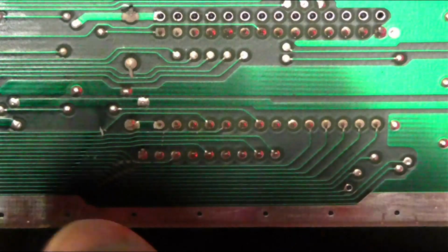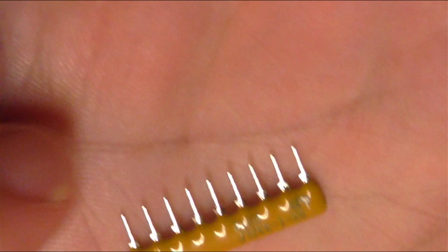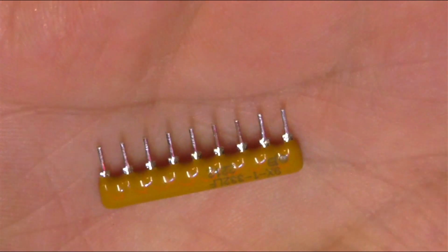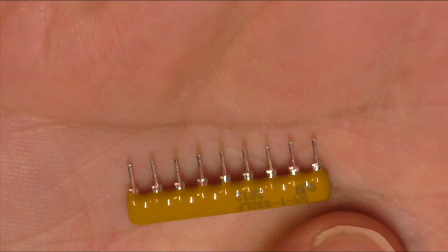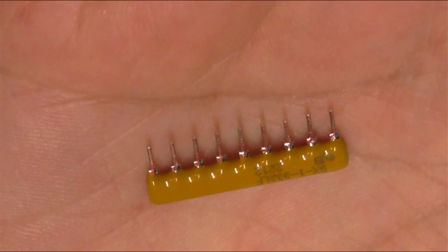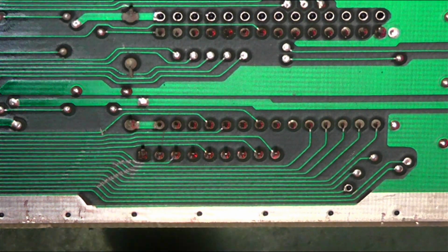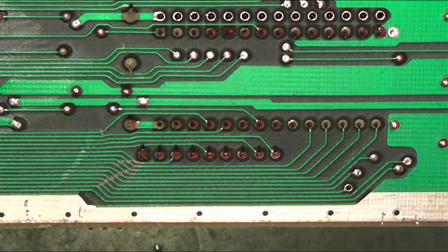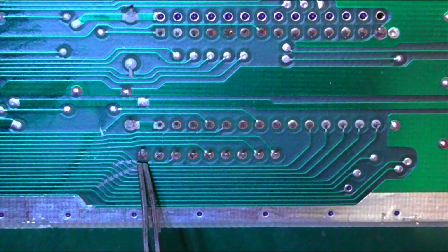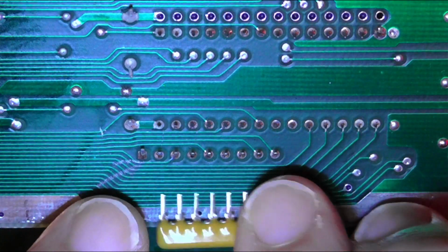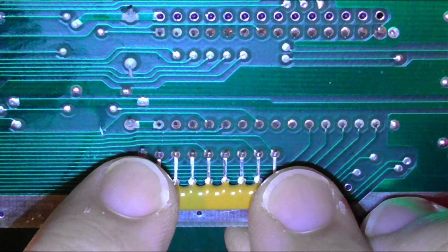So the way these work, I don't know if I might be zoomed in too far there. There we go. One side has writing on it, but has a dot. Do you see this? It's quite faint actually. That is pin 1. That is the common terminal. The common terminal on here appears to be, yep, don't know if you can make it out. Yeah, you should be able to. That is the square terminal, so that's in our case the 5 volts line.